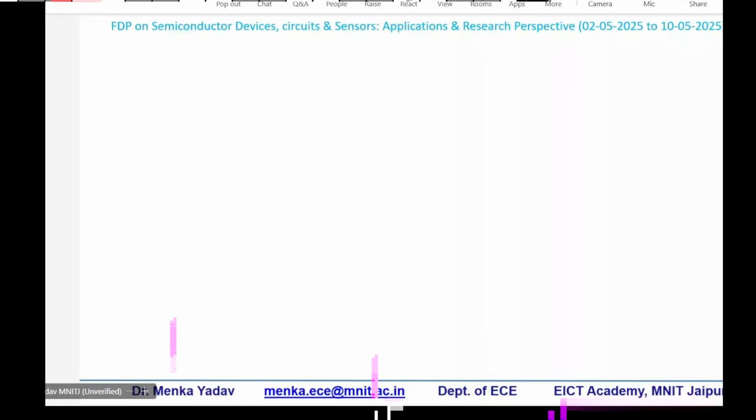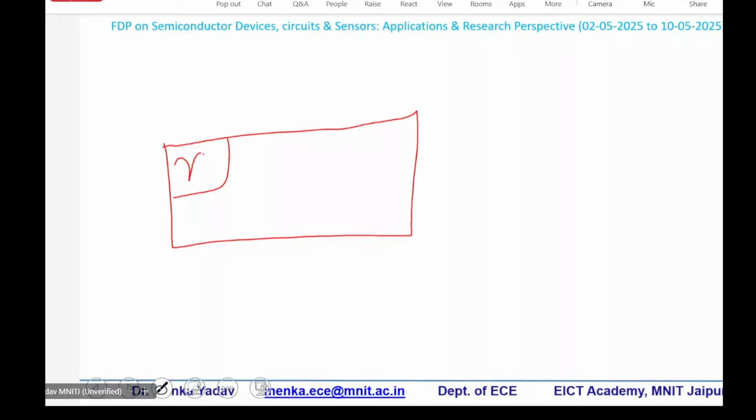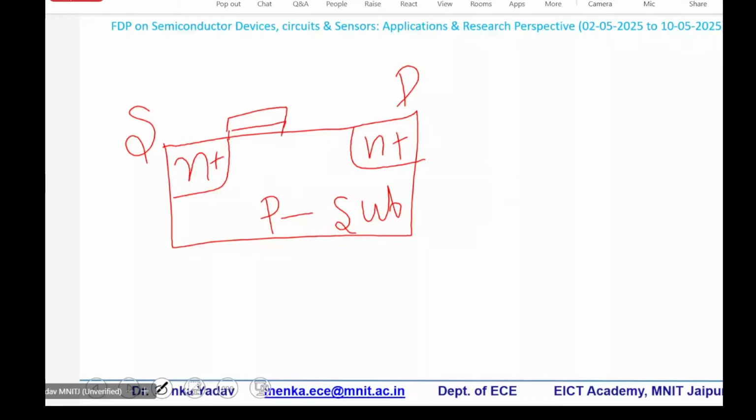So basically, this is your MOSFET, right? In your MOSFET, I have drawn N plus regions, which are nothing but source and drain. This is, let's say, the drain side. This is your source side. This is your P type substrate or body contact, right? Now, let me take my oxide from this to this, and this is my metallic gate. And here I'm going to put my gate. This is my source connection, and this is my drain connection. I have left this particular region as it is.